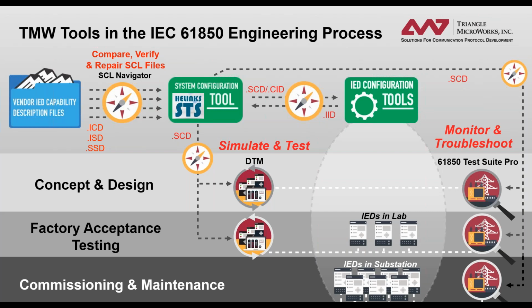The recommendation is that in the description or in the short address, we have a text that is more or less understandable for the system engineer what kind of input that is. Is it a blocking signal? Is it an initiate of a breaker failure function or whatever? In that case, the system tool, when it creates the connection, needs to connect that to the right point.